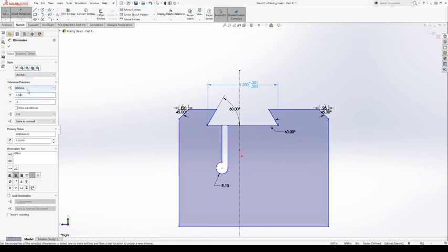I won't say common, but it's a way of dimensioning you will most likely see at some point in time. So even though this says plus minus, these are just maximum minimum values. You can have negatives in here. You can throw a negative in there. It will change how your tolerance is displayed, right? So we can put negative numbers in there if you want to. You can put positive numbers in there. They can both be positive. It doesn't really matter. It will display them, right? So anyway, that's bilateral tolerance.